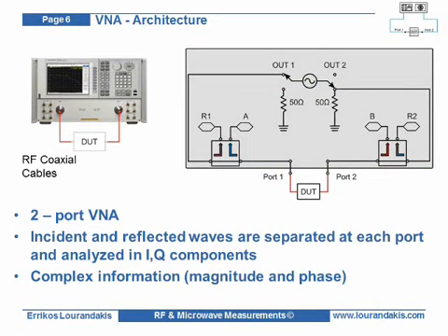The vector network analyzer is a measurement system for capturing complex network parameters for both reflection and transmission. For doing so, the network analyzer has a built-in frequency synthesizer that generates the sinus wave that is swept over the bandwidth of interest. At each frequency point, the reflection and transmission parameters are measured at both analyzer ports.